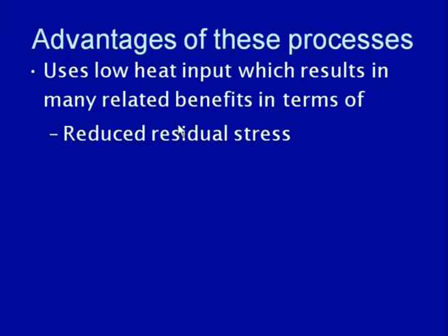These residual stresses many times decrease the mechanical performance and the corrosion performance during service conditions. So, if we reduce the heat input to the base material, then the extent of differential heating and cooling is also reduced, which in turn helps in reducing the residual stresses developed during the braze welding process.